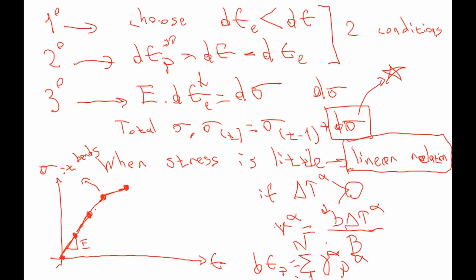It's not increasing at the same rate because the stress at the time being is the summation of previous stress plus the incremental stress, right? And the incremental stress is just the elastic strain times the modulus. And we are fixing the total strain. Since we have plastic strain, we are decreasing the elastic strain.